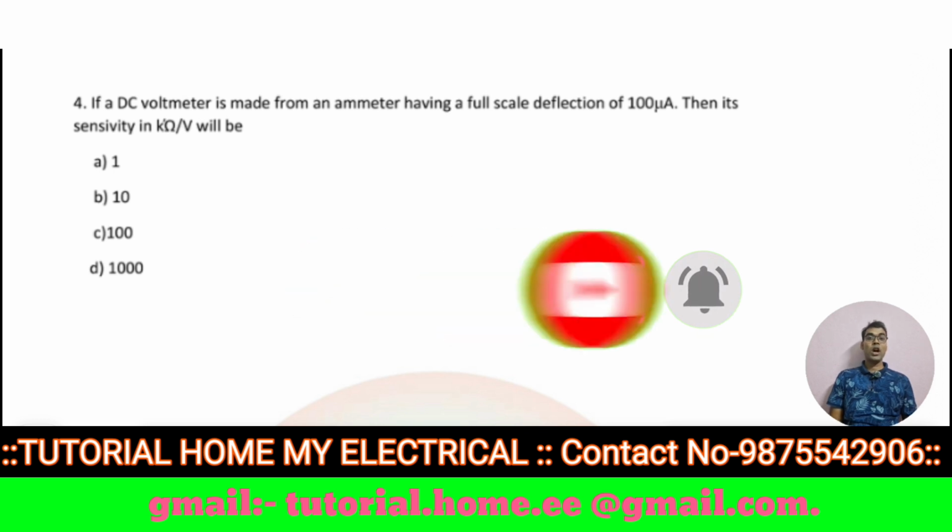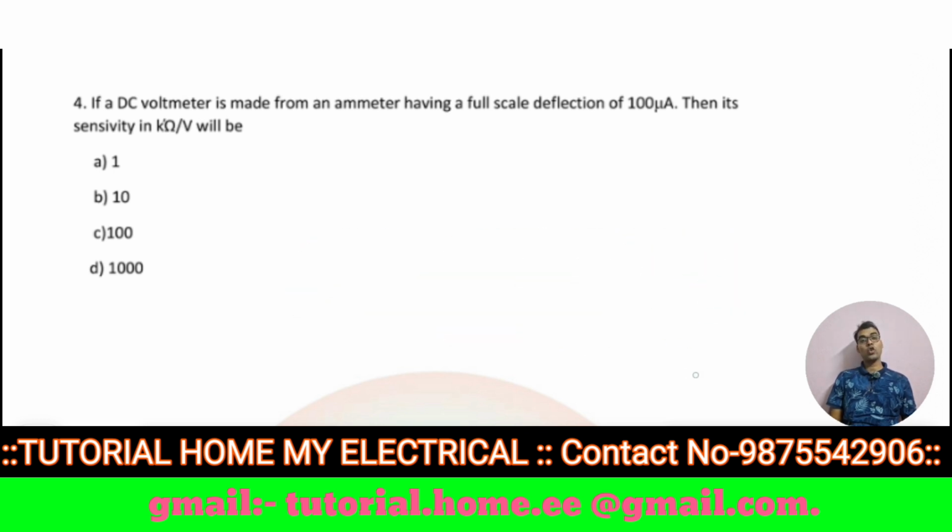In the previous part, I already discussed 3 questions. So in this part, I start with the fourth question. If a DC voltmeter is made from an ammeter having full scale deflection of 100 microampere, then what is its sensitivity in kilo ohm per volt? The question asks for the sensitivity in kilo ohm per volt.